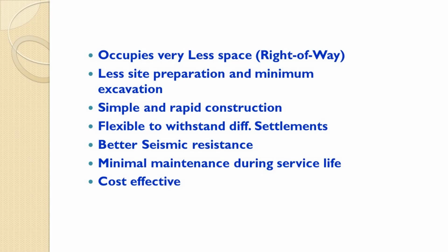So, why a reinforced soil wall? It's an application. So, we have to understand, it occupies very little space, less site preparation and minimum excavation, because the embedment depth is, in most cases, only 1 meter. So, less site preparation, simple and rapid construction, flexible to withstand differential settlements, and it is also better under seismic loading.